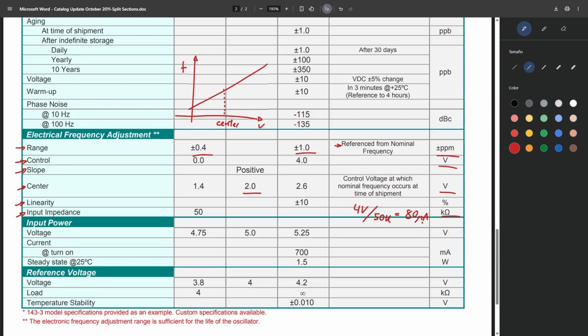Well, these values are okay, but again, they are just ranges. Maybe you will be thinking that if I want to thoroughly control the OCXO, I need to know the exact behavior of the device, and that I should calculate a graph of frequency over voltage. Then, to control the frequency of the clock, I will only need to input the frequency in the graph to get the desired voltage. But to this I have one catch. If you remember, the real values of the system will change over time. That means that the graph I calculate now may not be real after the device has been running for a few hours.